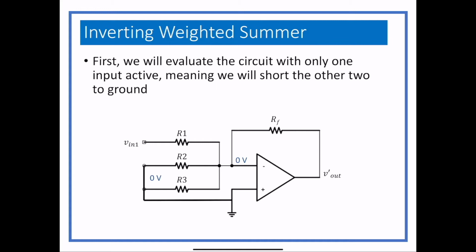They're like in parallel with 0 volts across them. That means they have absolutely no effect on the circuit, which is really cool because we can completely eliminate them.